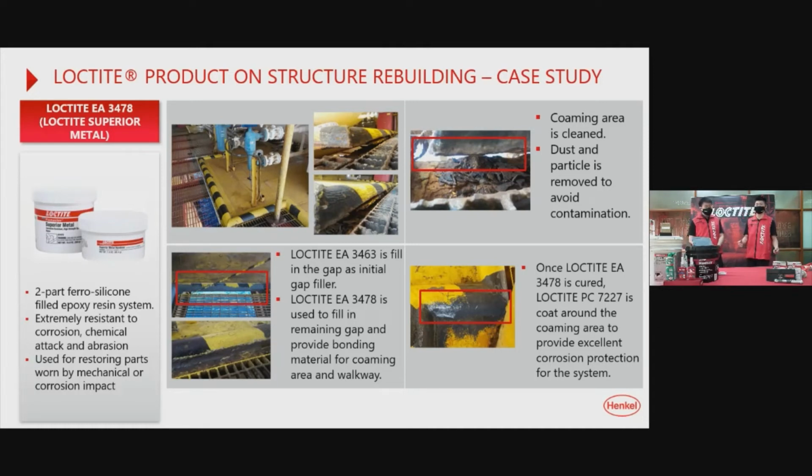The reason is the thermal expansion, what we know as the coefficient of thermal expansion. The putty is designed to resemble the substrate, so that it is able to expand accordingly. Without the same coefficient of thermal expansion, it will cause what we know as premature failure, or an unreliable protection or repair for the substrate itself. All right. Okay.